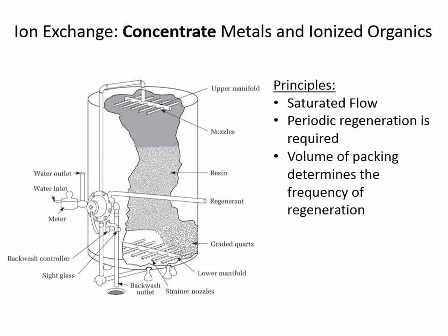So we have to stop the dirty water from coming in during the regeneration process. And let's say it's going to take a smaller amount of time, maybe just only 1 hour. What we would do is we would redirect this regenerant through here, and then out of the top we would take very dirty water.